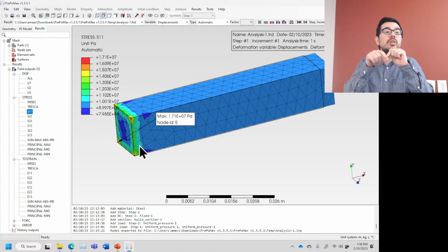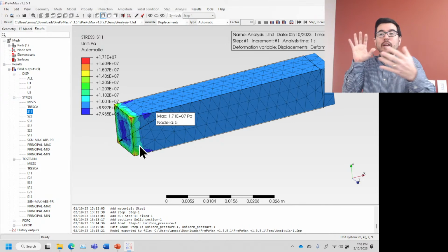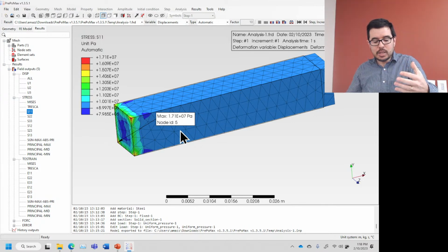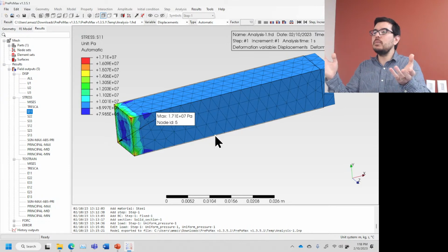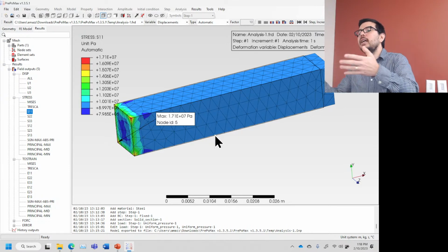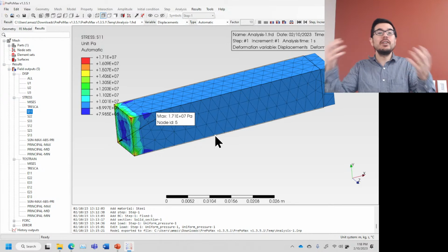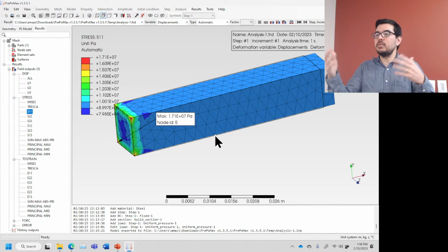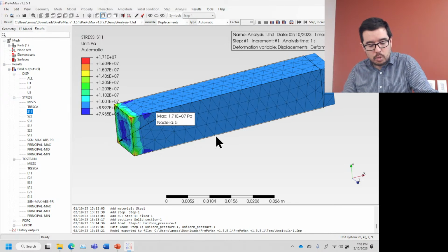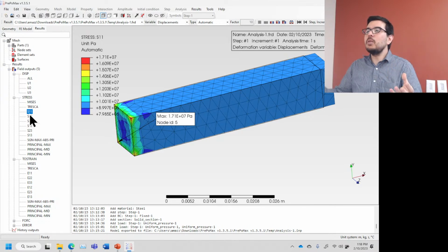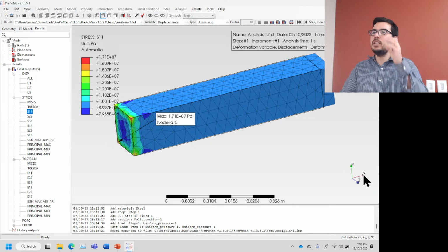It's not allowed to move, right? Whereas over here, once we're sufficiently far away, and this is called the Saint Venant principle, once you're sufficiently far away, you can approximate things nicely, shall we say. That's a really bad way to say it, but you can approximate as just force divided by area, essentially. So this stress, now what is S11? S11 is sigma 11, all right, or sigma 1, or in our case, sigma x. Remember that? We have that notation.